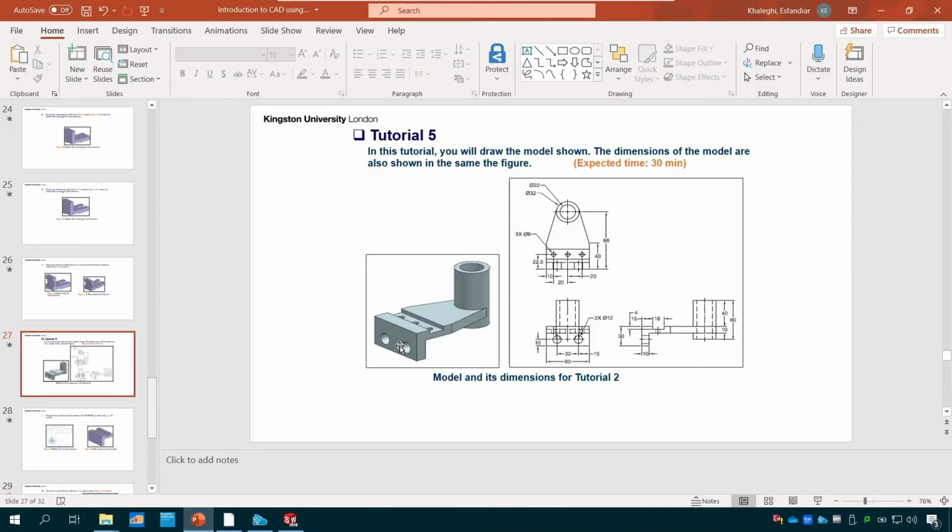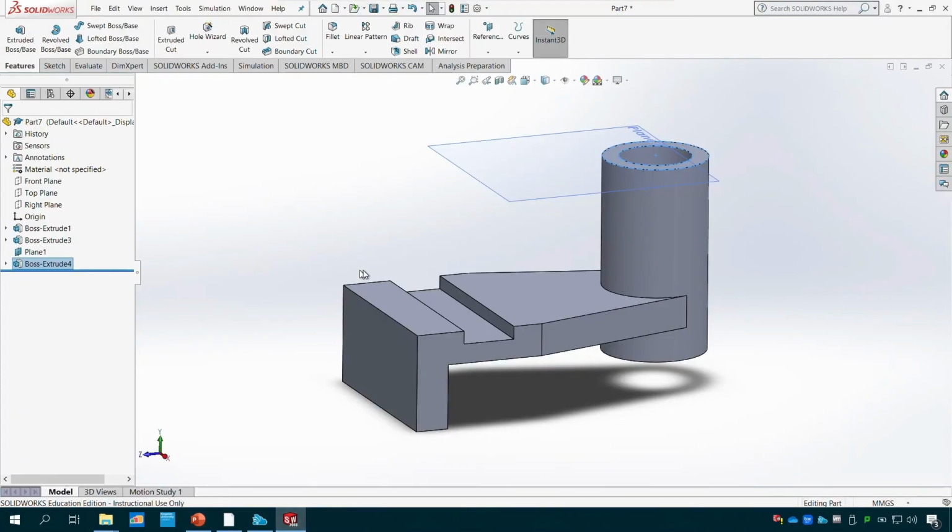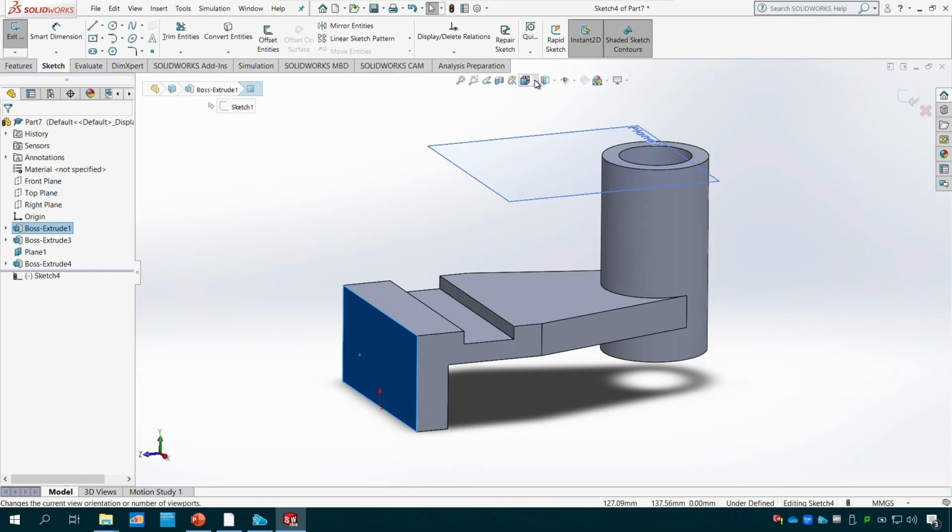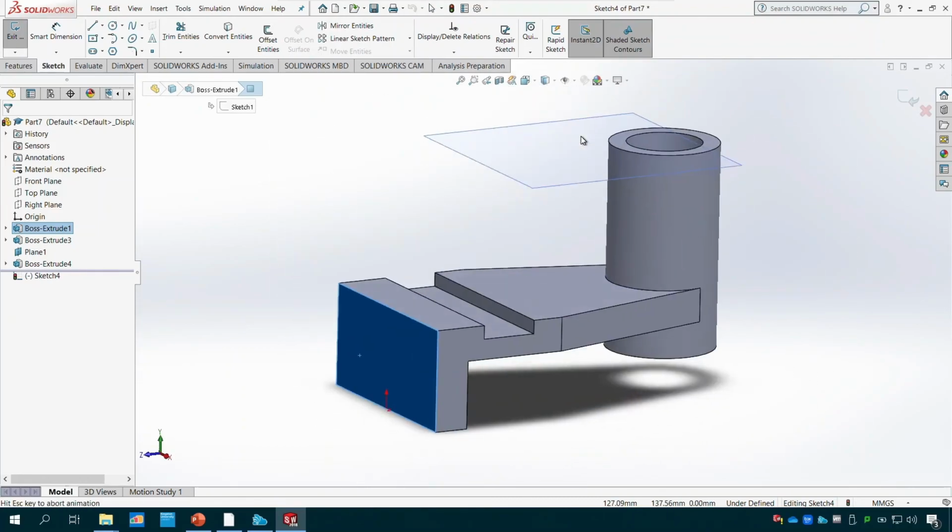So now you can see I'm gonna create those two. You can do that using 3D, but because we are learning 2D modeling, I'm gonna do it through the sketch, but of course you can do it through the 3D and create a hole. But let's go using the 2D modeling. So what I need to do, I need to make those two using the sketch on that plane. I'm gonna pick up that one, go to the sketch, click on a sketch, make sure I put it to the normal too.